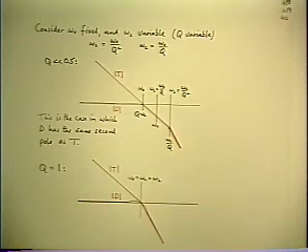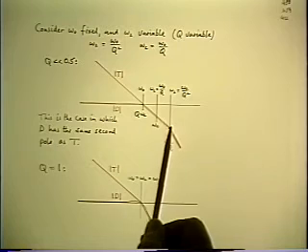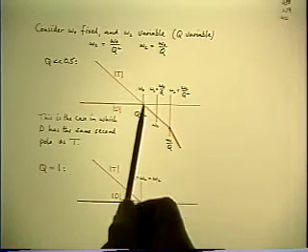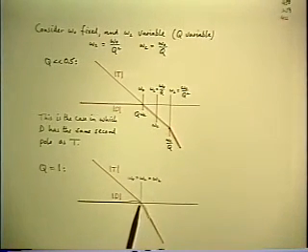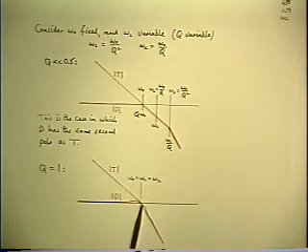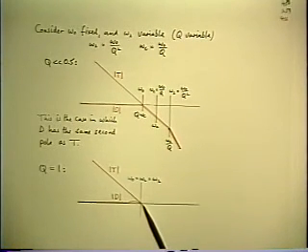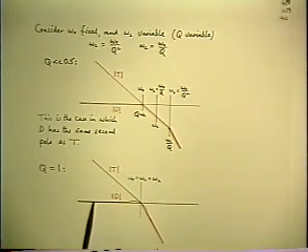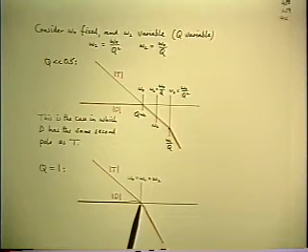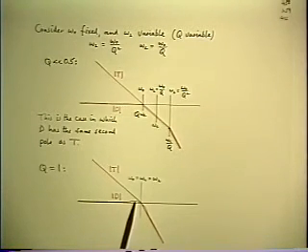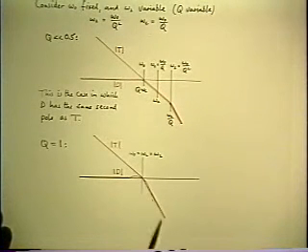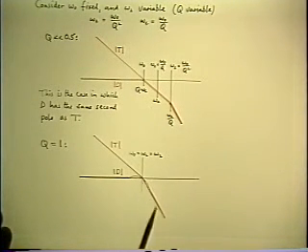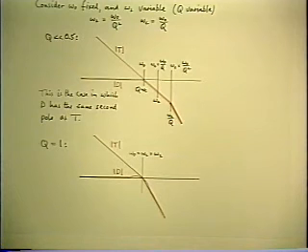Now, the next interesting case is, what if Q is 1? Q is 1 if the omega 2 comes back down to be equal to omega 0. So the second pole in T is at the original crossover frequency. So the shape of the quadratic with a Q of 1 means that D is 0 dB and goes through unity at the corner frequency and bulges up a little bit below it, and then bulges up above the other asymptote and falls off at a double slope.